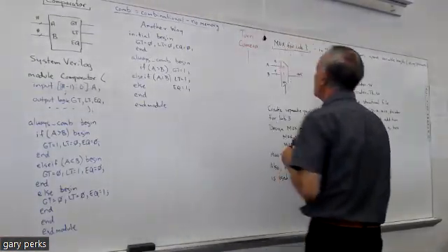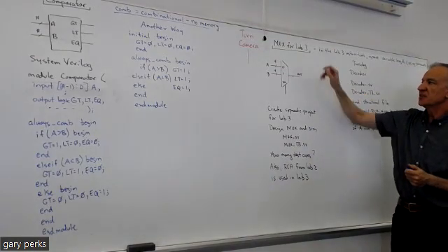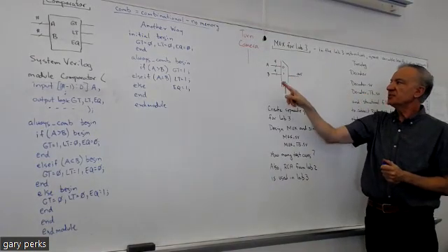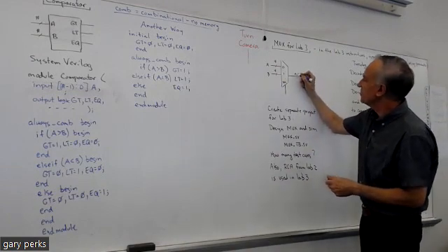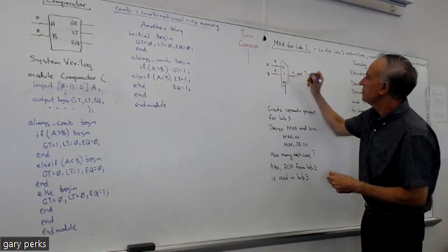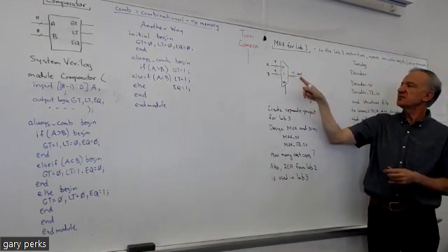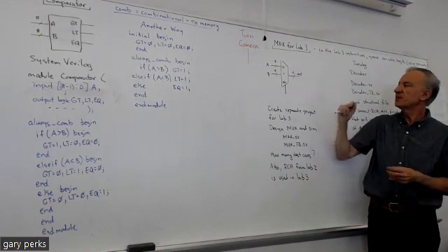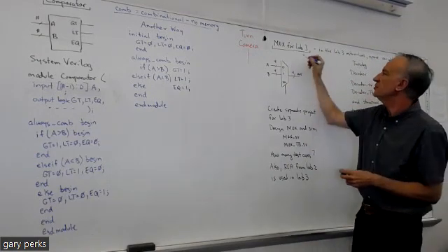All right, because here's the mux that we want you to design for lab 3. It has 2 inputs. Forgot to do this, but the output's also 4 bits, so there should be a /4. So it's got two inputs where each input is 4 bits, and like always, it's one output, because all muxes have one output, so this is a 2-to-1 mux.